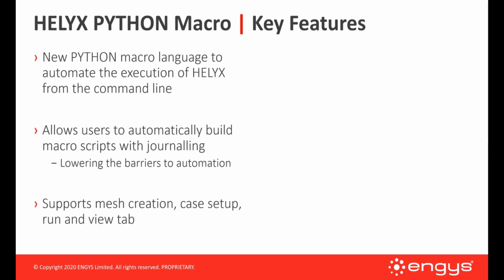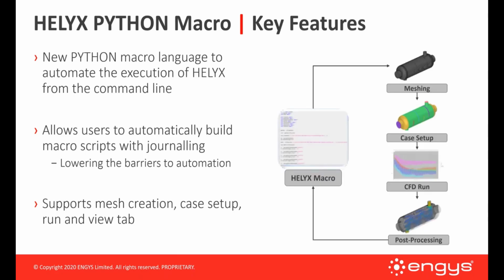Right now, it supports mesh creation, case setup, solving, and then also post-processing. And overall, the process is, we use this macro language to drive all of these in sequence, or in theory, we could just break things up and do each one of these individually. For example, if you just wanted to generate 20 different meshes, you can do that if you want to do a sensitivity study on base mesh spacing to see exactly what your cell count might be.